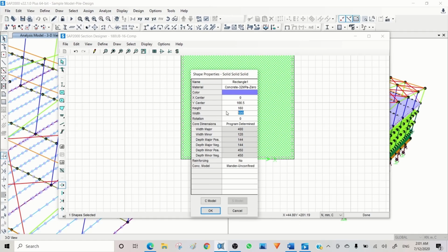I assume 1 meter. As I said before in our webinar, because the concrete and the steel don't have the same modulus of elasticity, we need to convert the concrete size based on the modulus of elasticity ratio. Roughly the modulus of elasticity of concrete to steel is about 1 to 10. It is not necessarily correct here; you can calculate accurately, it could be 1 to 8, but let's assume 1 to 10 at the moment. So I need to reduce the width of the slab to 10% of the actual width.